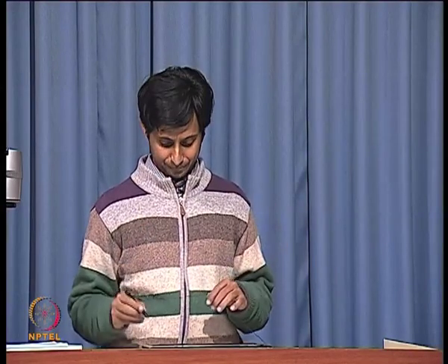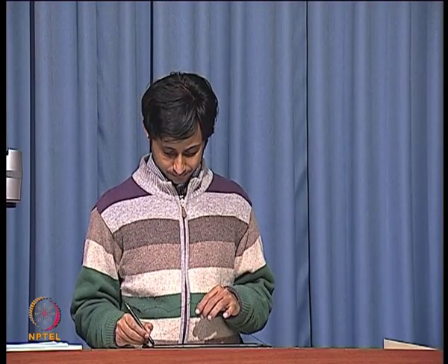It is not something that I want. 2 f2 minus f1 is also very close to f2. It is not something that I want, right. So, this is what basically creates the problem. How do I solve this? Well, one thought is, why do not we pre-distort the signal?